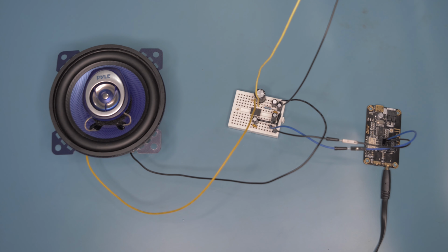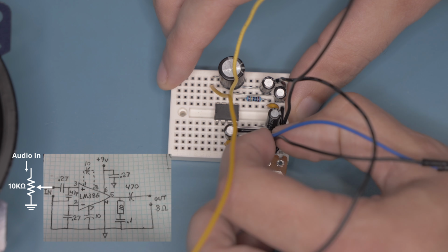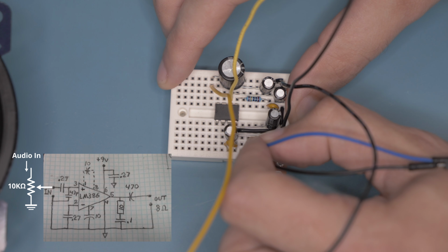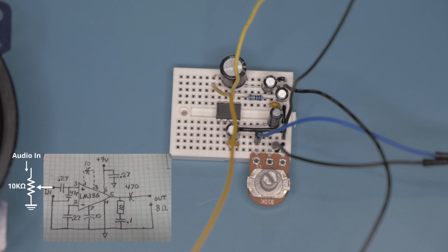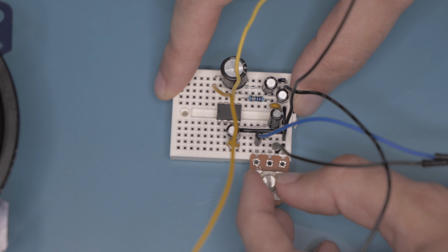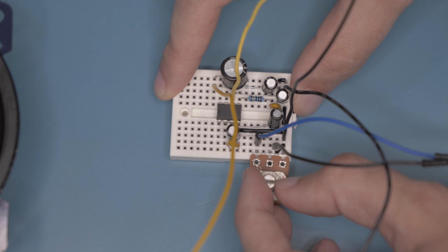Before trying to address the distortion, let's put in a 10 kilo-ohm potentiometer so that we can control the volume. Rather than trying to use the potentiometer after the amp, we should actually place it before the amp. Also, if you use a regular linear potentiometer, it will sound like this. It's easier to tell in person, but moving the pot even slightly causes it to very quickly go to maximum or 0 volume. It's not a gradual change.